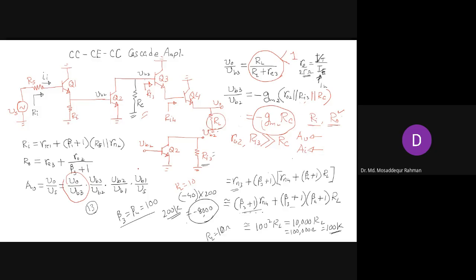Any question, guys? Sir, now the gain is not dependent on Ri3. So what if we remove Q4? What if we remove Q4? Oh, remove Q4, then you get a low value for Ri3, that we showed in the previous calculation. Ri3 will be 1K. So if you are taking RC, let's say 10K, to have a high gain, the overall resistance will be reduced to only 1K or less than that. So that will reduce your gain.